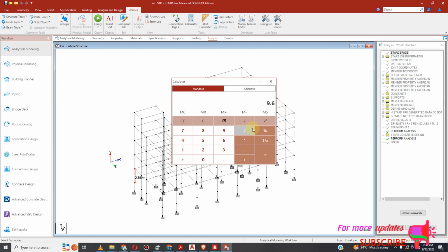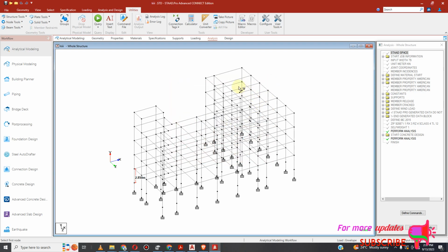So the other thing that I need to calculate is my parapet wall. So my parapet wall will be, I'm using 0.2 multiplied by now 1 meter, 1 multiplied by 20. So my parapet wall will be 4. So let us add those weights.